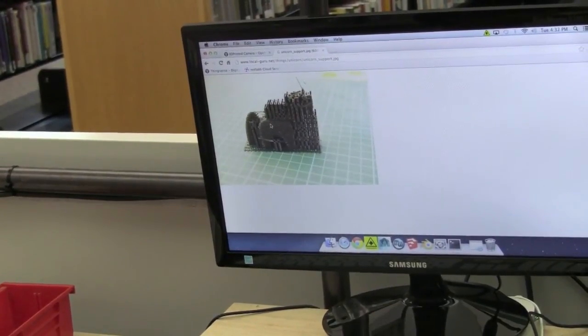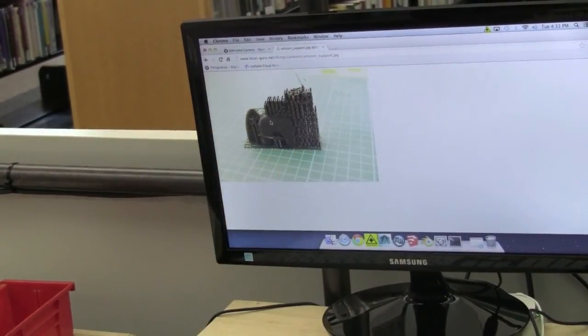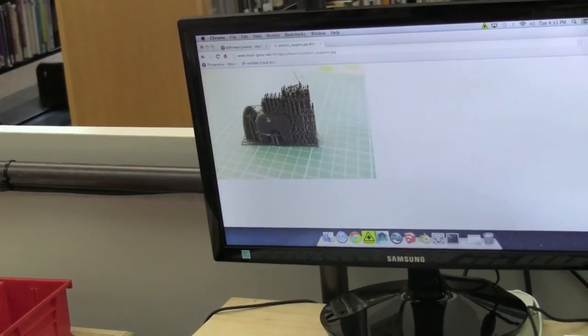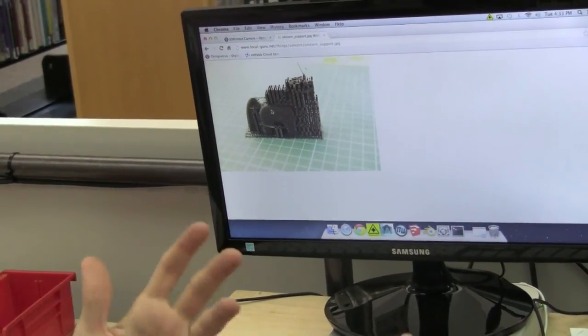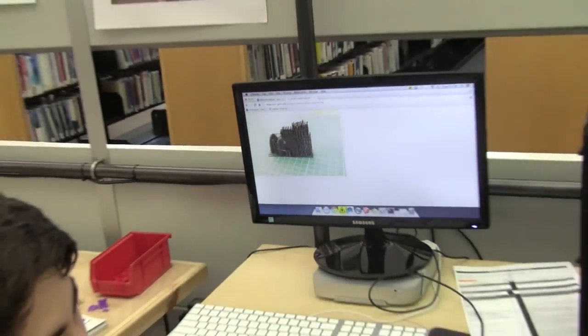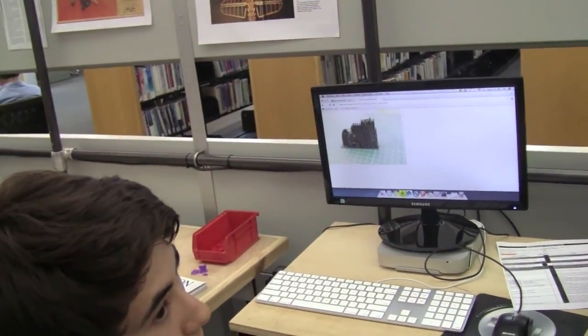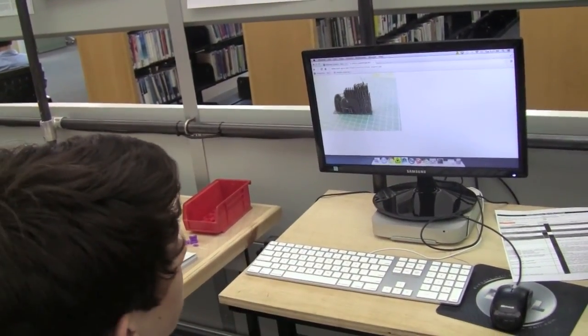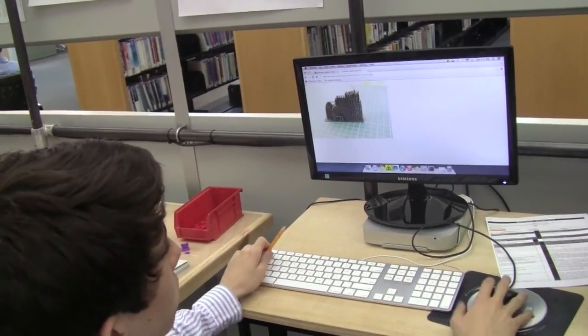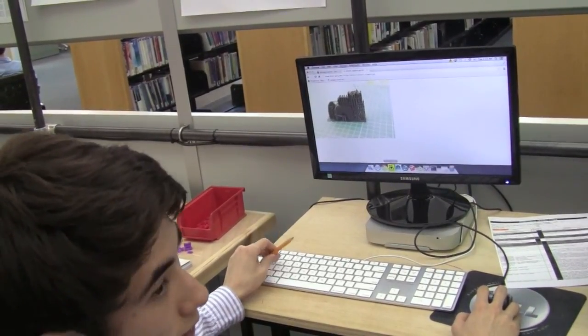That came up and cut way in. Right, yeah, and then it went back up. Then the support structure would help that part that overhangs. Right, but the only problem is if it's a bottle, you can't really get it out, and it's no longer really a bottle because it's filled with plastic. So normally I don't use full support if it's something like that.